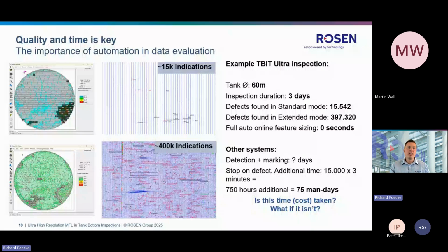So we cannot steer the tool from the outside of the tank, so there's still the need for the operator to be inside the tank. But with this, we enable the tool to move under obstacles like heating coils. We need a minimum clearance of 250 millimeter, but that is possible in remote, while steering completely from the outside is not possible.